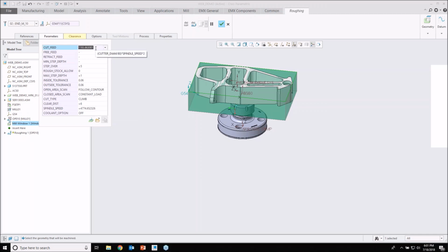It's just a start thing, so you can see it. I won't always use it. It depends on your tools that you have and everything like that. So normally I'll change this. So we're sitting with it. I need to change this as well to the 16 cutter in any case. So I'm going to go for a smaller step over, and I'm going to cut a little bit deeper with this particular tool. So these settings will be determined by the tooling manufacturer. That's the only things that I really need to specify in here.